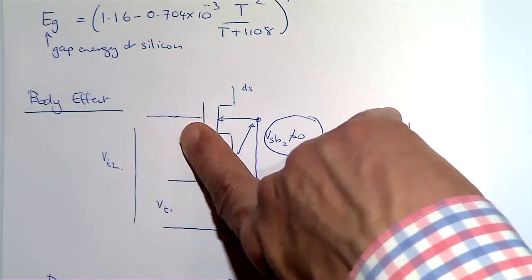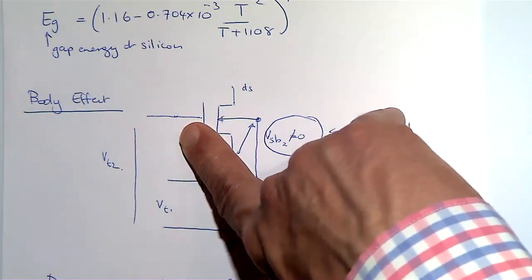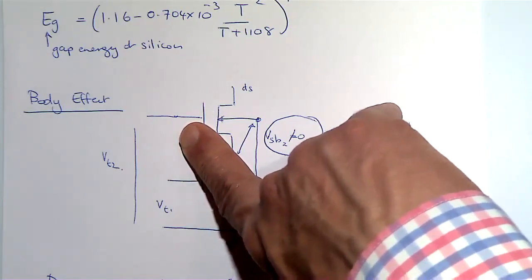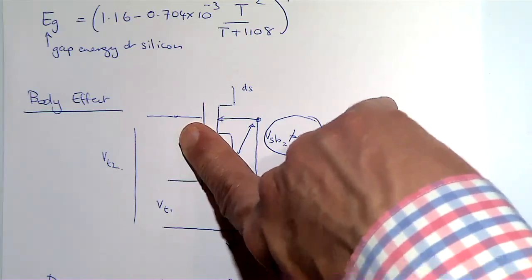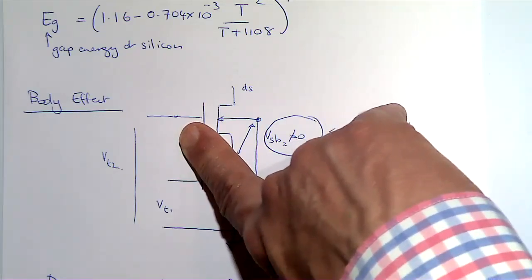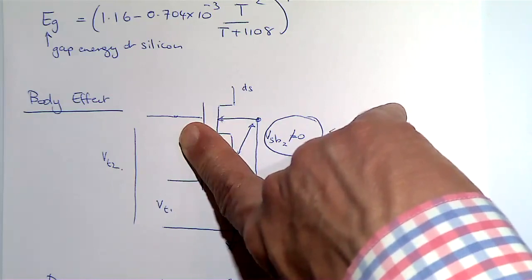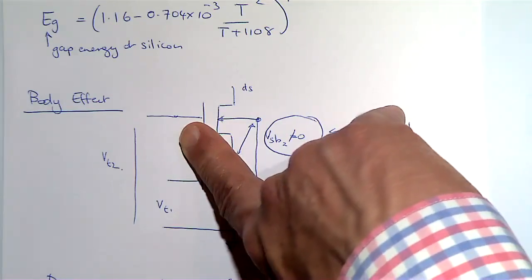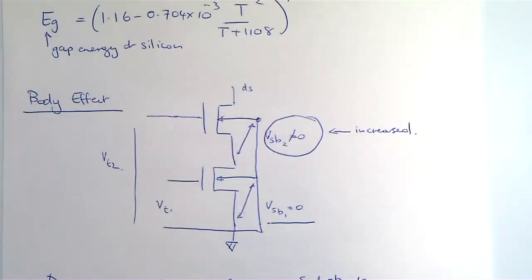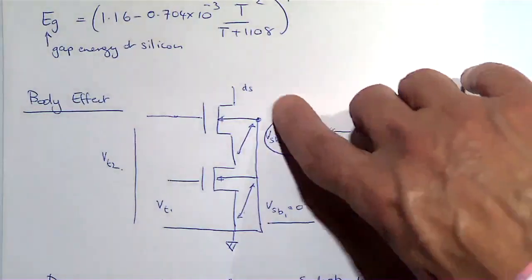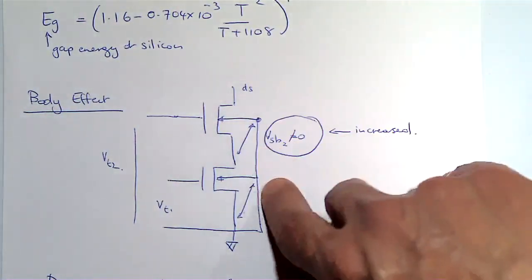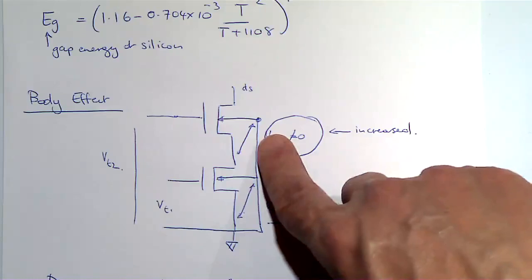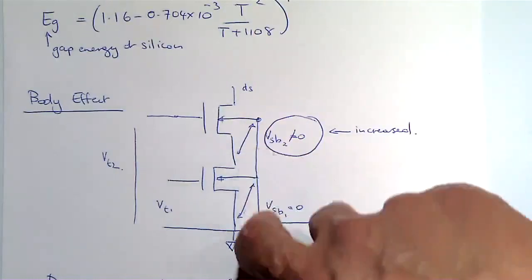So maybe you'll go to 1.5 volts, but nonetheless 1.5 volts squared is at least a significant increase relative to if you only were able to swing 1 volt. And this is an important trick that you use when you're trying to build amplifiers or other types of components on a chip.